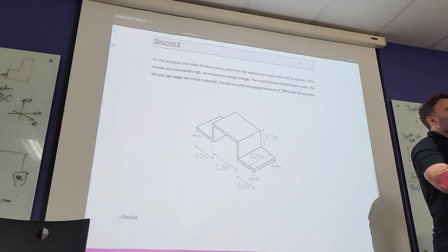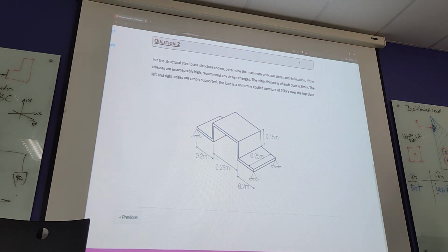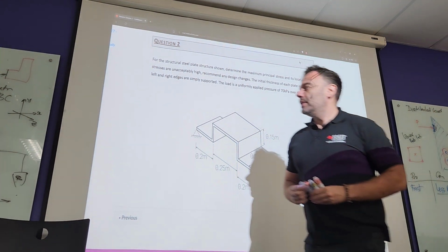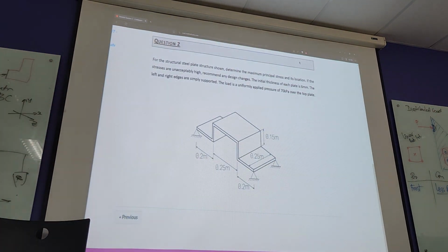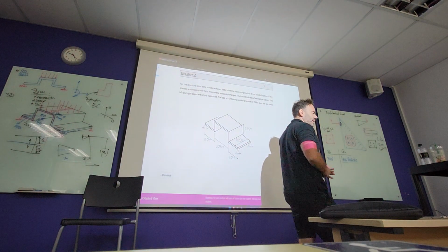There'll be some variations for thickness. You have 3D solid will give you more detail. So you may realize that, for example, due to boundary condition, we'll have a region here that is highly stressed. Shell may not pick up that much. But roughly, generally, you have it.